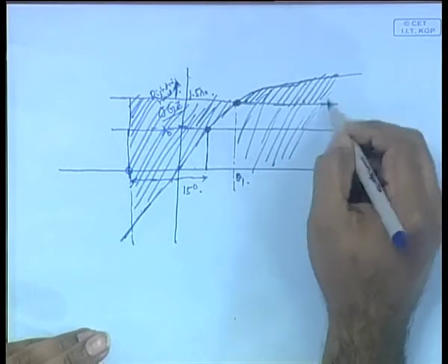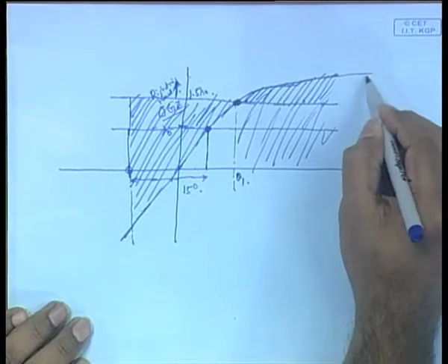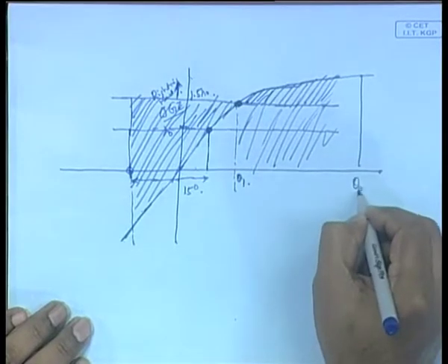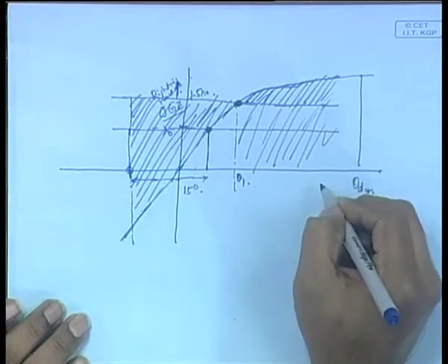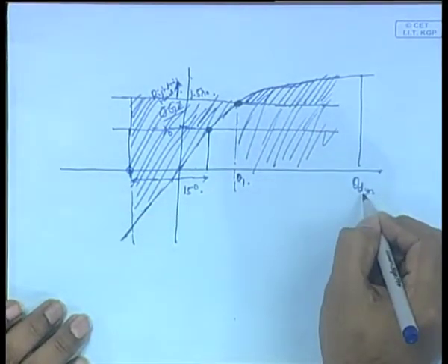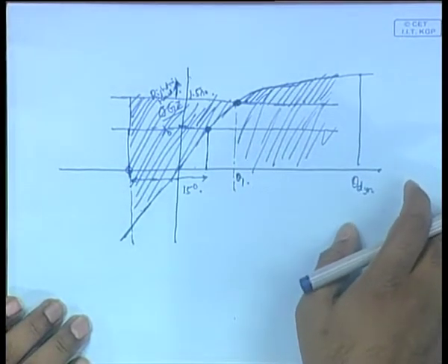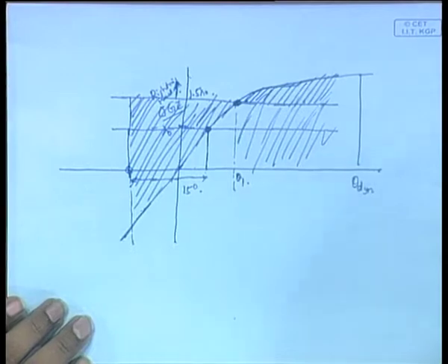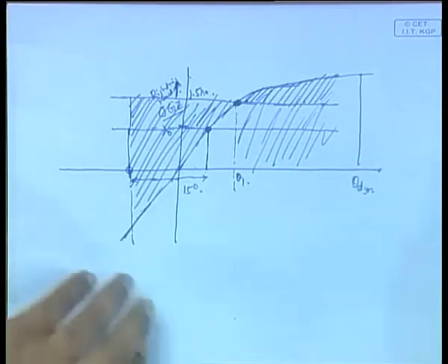Okay. The whole area under the GZ curve, starting from wherever it is starting, goes till some value theta dynamic, till this area is equal to this area. So, you reach theta dynamic, and this theta dynamic should be less than some flooding angle. Okay. So, if you want, I can explain this again. It is like this. I think I will do this. This is a little confusing.